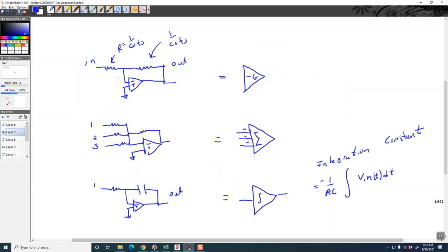Well, if you know an inverting op amp, it's the same structure, except now the resistances are programmable. So you have just a triangle symbol with a minus gain stage. Right here we have an inverting summer, and everything can be programmable. Everything's inverting, and you can actually have each line coming in with an independent gain.